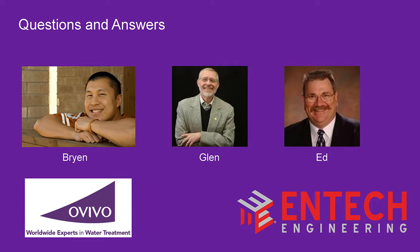Thank you, Ed. Dr. Diger, I think you would be the best person to answer this question. How do you control the nitrogen and phosphorus released from the biomass decay in the aerobic digester to a low level? So let me separate it into the nitrogen and then the phosphorus. For the nitrogen, the simple answer is that you control the released nitrogen by converting it into nitrogen gas.